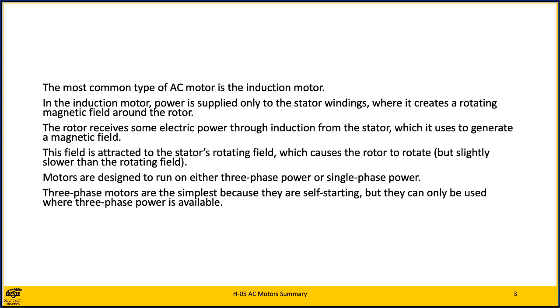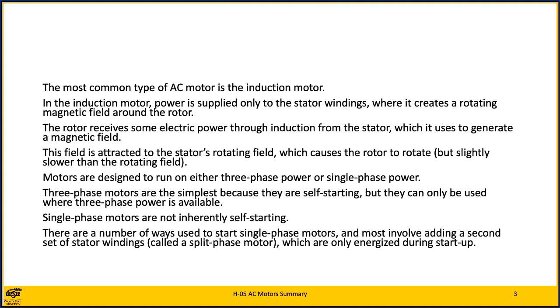Three-phase motors are the simplest because they are self-starting, but they can only be used where three-phase power is available. Single-phase motors are not inherently self-starting. There are a number of ways used to start single-phase motors, and most involve adding a second set of stator windings, called a split-phase motor, which are only energized during startup.